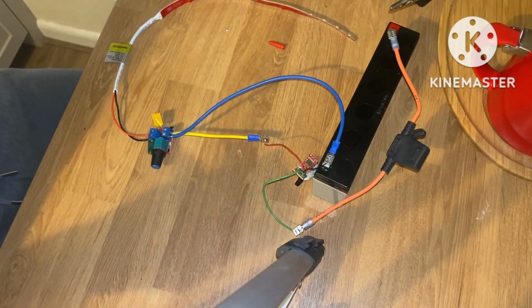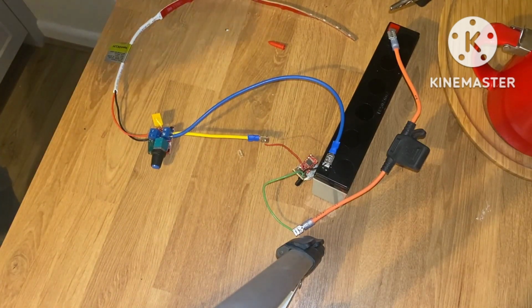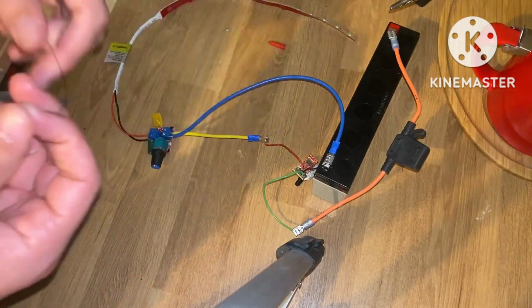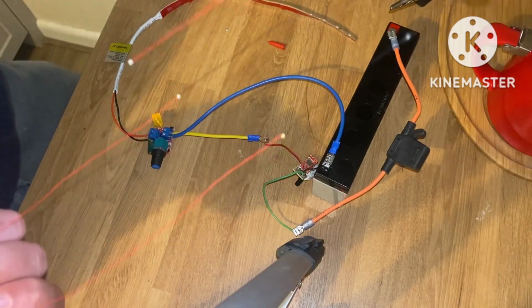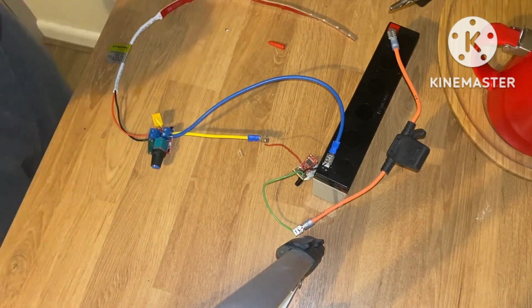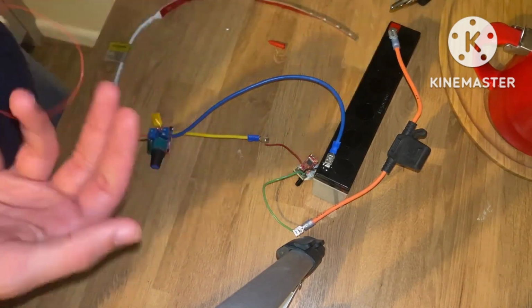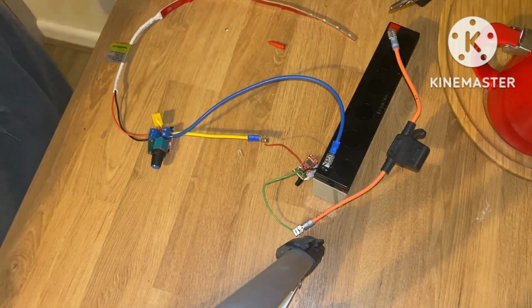When I have 4 in a string, you take your supply voltage and divide it by 4, and that's what voltage they get. So if I'm getting 12 volts out of the power supply, each one of these will see 3 volts, so comfortably within their range. But obviously I've got the resistor in there, which uses up a bit of voltage, so they'll actually see slightly under 3 volts.